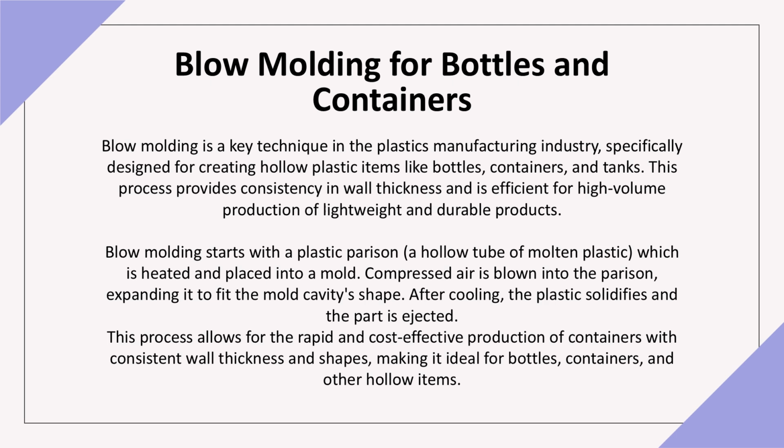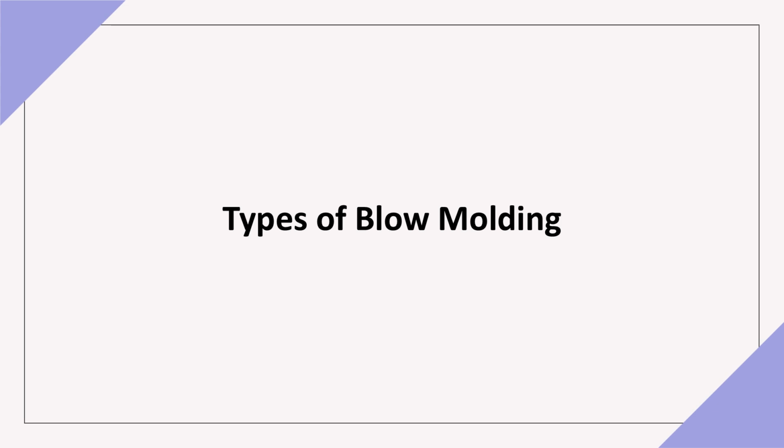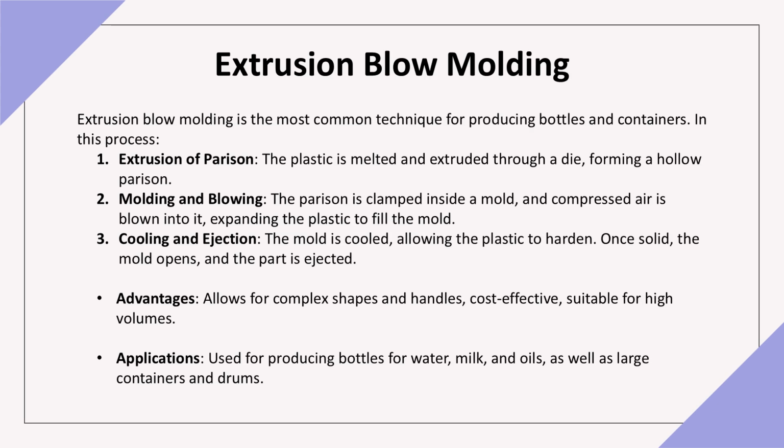This method is particularly effective for high-volume production, offering consistency in wall thickness and producing lightweight, durable items cost-effectively. Blow molding has several variations, each suited to different product requirements. Extrusion blow molding is ideal for producing bottles and containers.